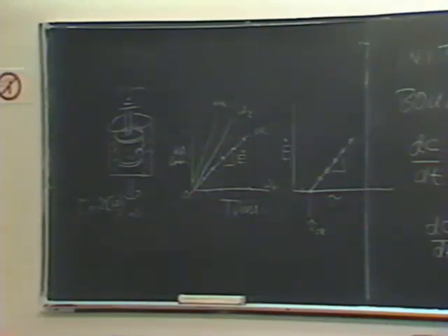But if you make up a soil sample, say a montmorillonite sample, you consolidate it so that it's firm and will stand in this apparatus, and you put salt water in it, you'll find that you go almost to the limit of the apparatus' ability to provide shear stress before anything happens at all. If you put distilled water in it, at about 20 dynes per square centimeter, it all starts to come apart. And so that's absolutely right. The composition of the water is very important.